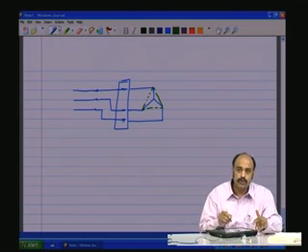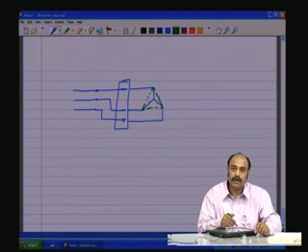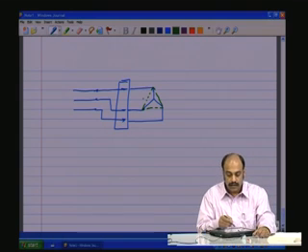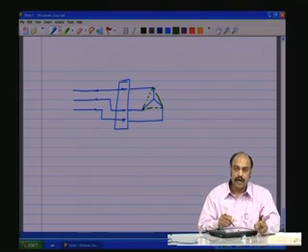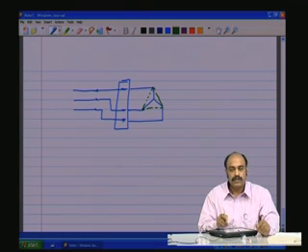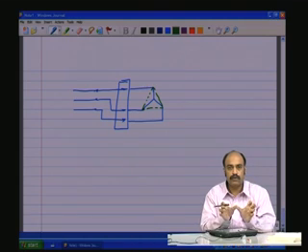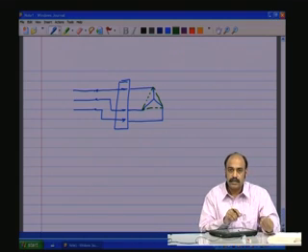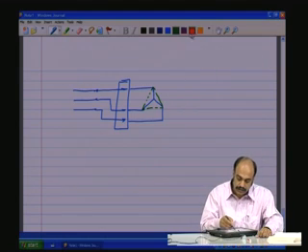So you have two possible voltages that you can apply in star delta fashion. In the star fashion, you have E line by √3 applied across the phases, and in the delta fashion you have E line applied across the stator coils. So you could have two possible voltage values applied to the stator coils, and therefore the range of the motor can be slightly extended, which is basically the same as the stator voltage control.